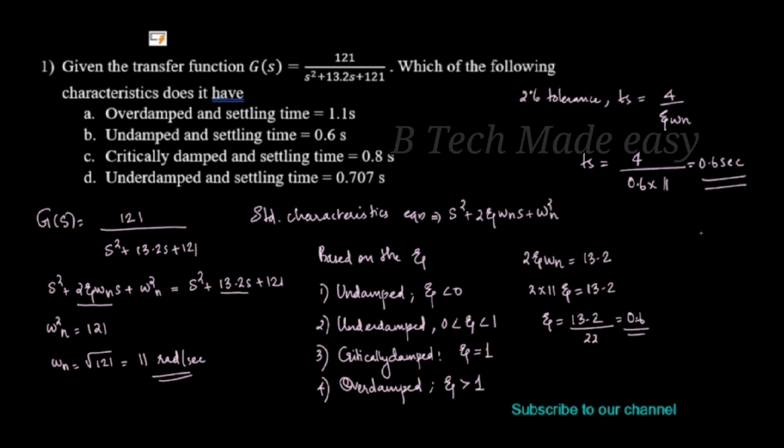Okay. Now I have to find the value for 5% tolerance. This is the standard tolerance ratio. So for 5% tolerance, Ts is equal to 3 divided by ζωn.